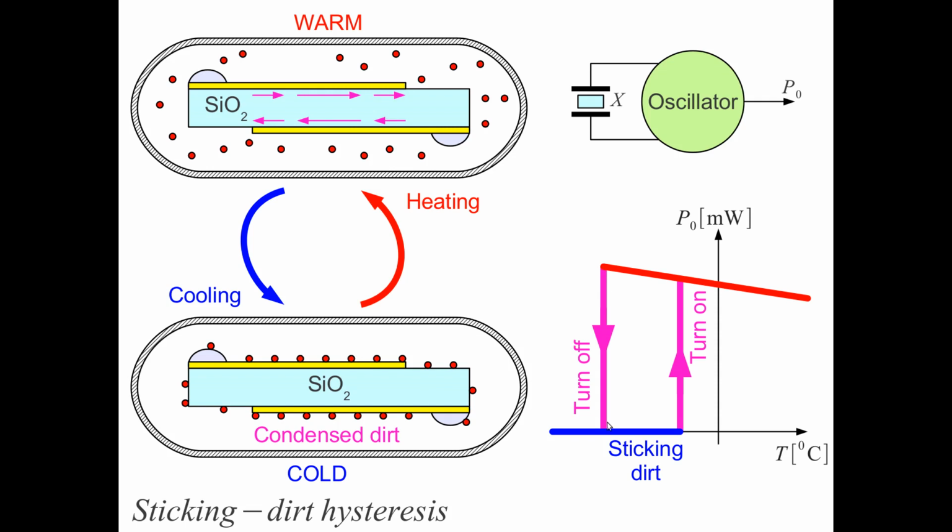So a typical problem of crystal oscillators, even in cheap electronics with microprocessors, is that microprocessors will not work below 0 temperatures because of bad crystals. And this effect is not repeatable because we do not know anything about the manufacturer, and his products are not repeatable. So different crystals may have different amounts of dirt vapors inside their package, and this effect may happen at different temperatures.